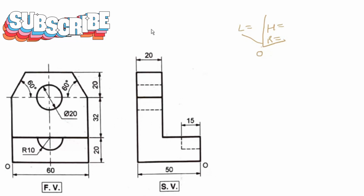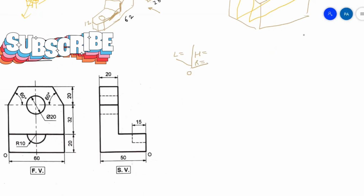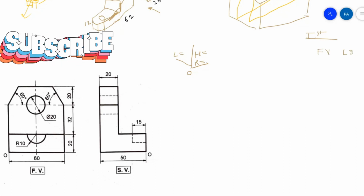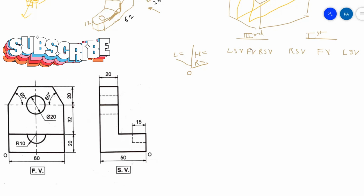We don't know whether it is first or third angle method of projection because the top view is not given. So in first angle method of projection, how do we draw? We draw the front view here, the left side view here, and the right side view here. And if it is third angle method of projection, then what we do is we draw the front view, the right side view on the right side, and the left side view on the left side.